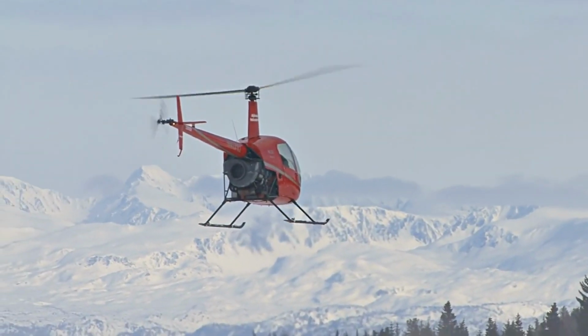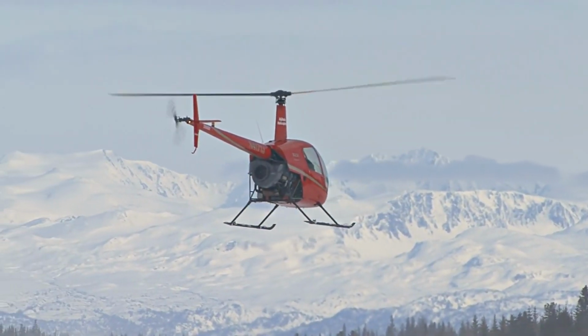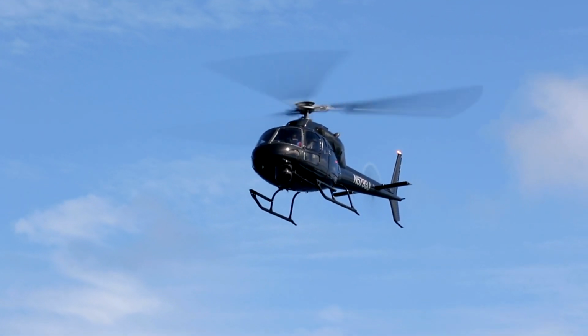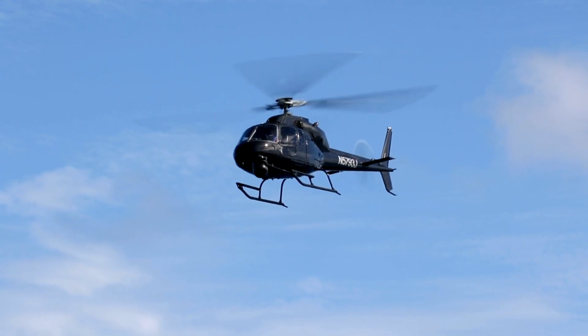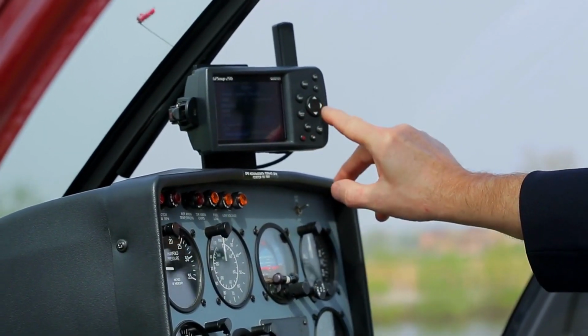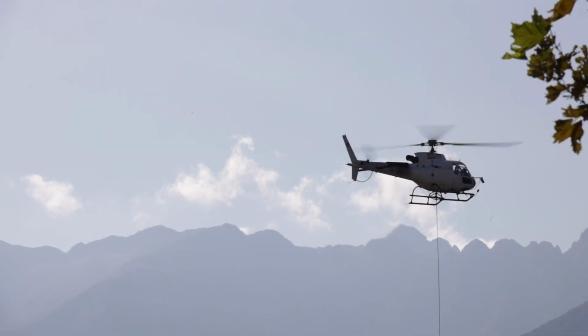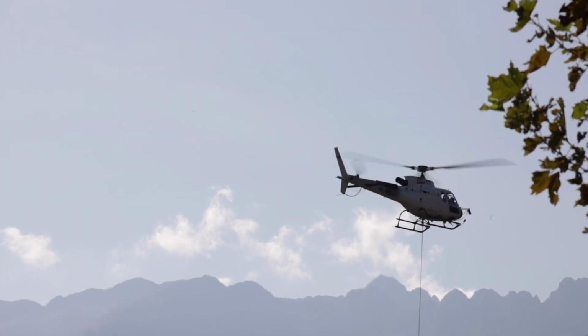Yet, even in this aerial waltz, common errors persist. Maintaining a slow, constant rate of turn is critical, as is the steady positioning over the reference point. RPM must remain within the normal range, and altitude should be unwavering. Proper use of anti-torque pedals is imperative to the success of the maneuver.